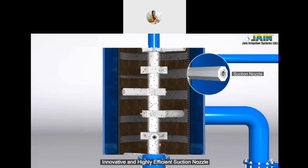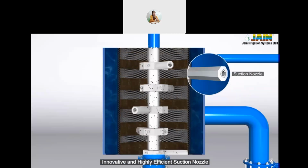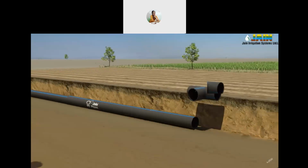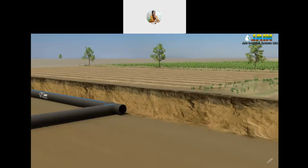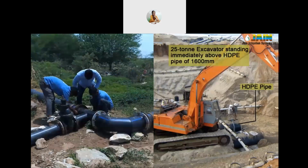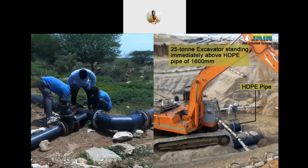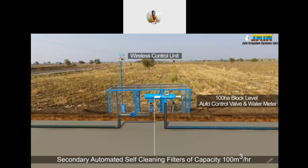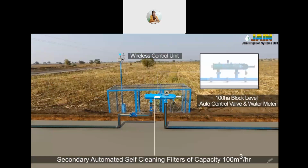The filtered water further flows through high-capacity, high-strength HDPE pipe rising main. These pipes have an estimated life of 100 years. They can withstand abusive field conditions and are easy to repair and maintain. Water then enters the block of 100 hectare, where it is again filtered through fully automatic, hydraulically operated, online smart clean hydraulic filter to ensure that only clean water enters the drip irrigation system.